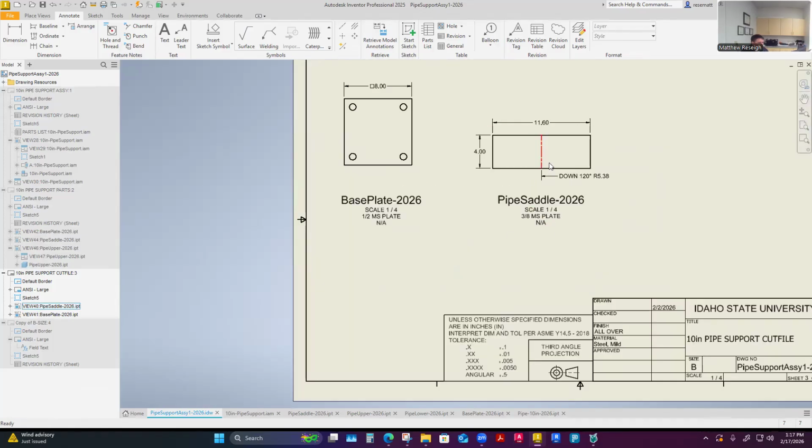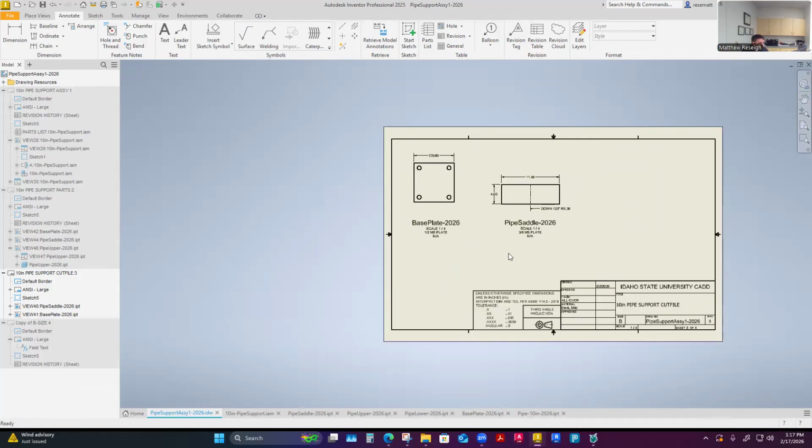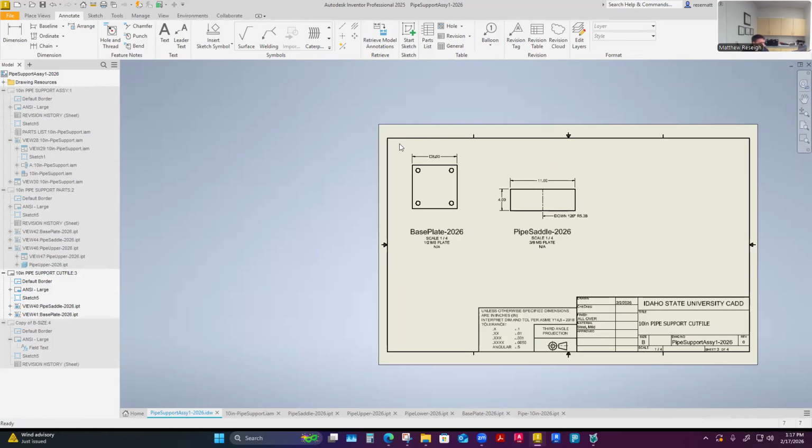My people are going to cut these parts for me, and they'll know that this is 1/2 inch and this is 3/8. Some places will add that redundantly, like adding a multi-text box to break things up, especially if I have more parts than just this. If I have a lot of parts, I bundle them by material type and what I can fit on the sheet and then the next sheet.